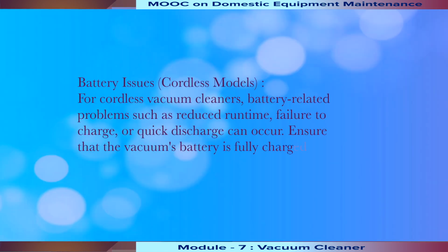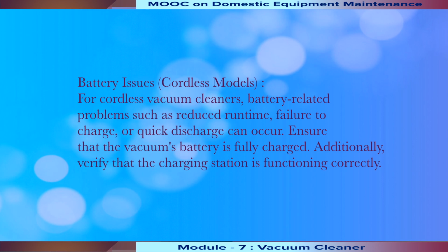Another issue is the battery issue. For cordless vacuum cleaners, battery-related problems such as reduced runtime, failure to charge, or quick discharge can occur. Ensure that the vacuum's battery is fully charged. Additionally, verify that the charging station is functioning correctly.